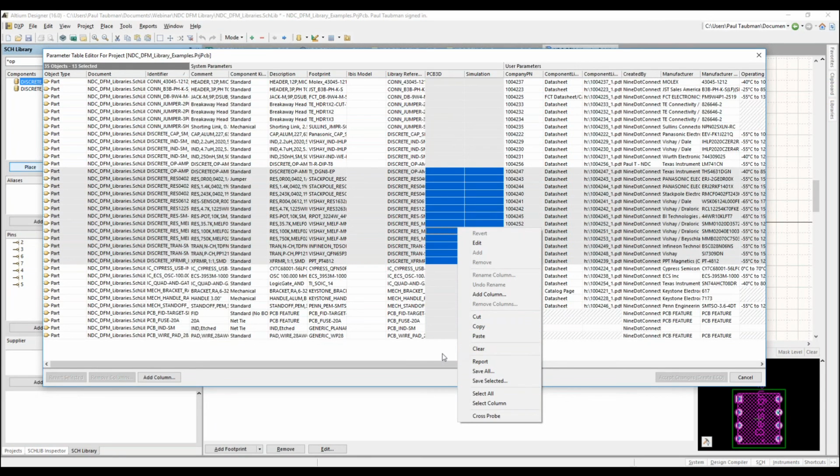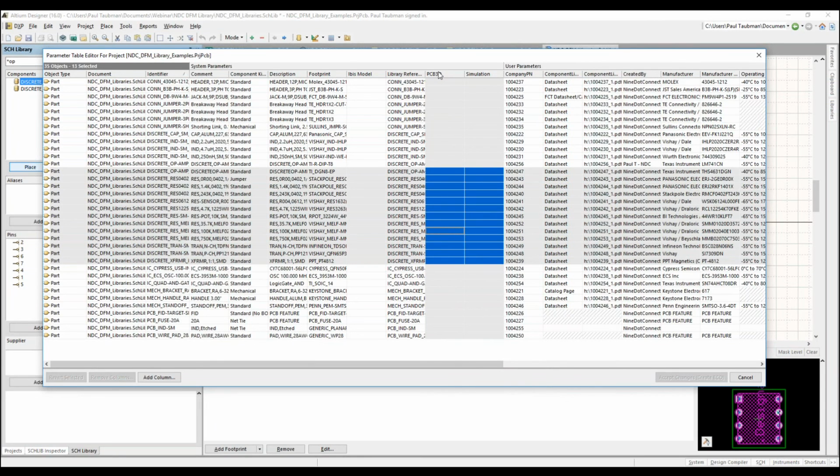I caution you on one thing though. If you click on the top header here, it's going to resort. So make very certain you know which one you're sorting on. Take the information that you want, write it up in Excel, and paste it in as a whole. And by the way, one thing I like about this is you can make whatever mistakes you want. It's only when you hit the Create ECO button and you execute on it that those things are going to take effect. So if you turn it into hash for some reason, you can always bail out.